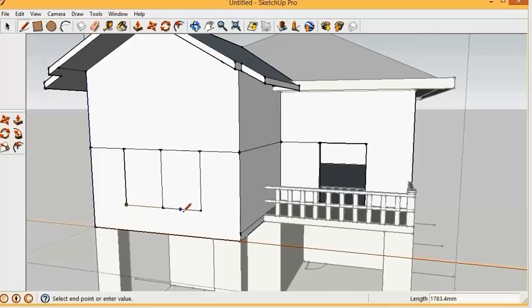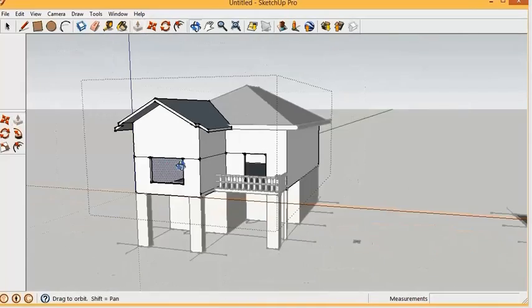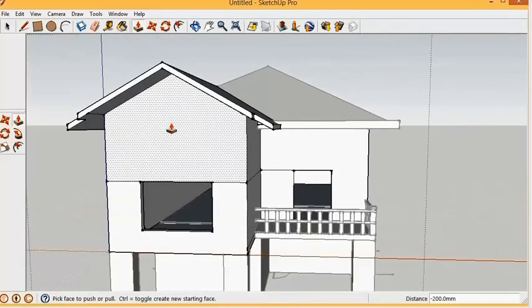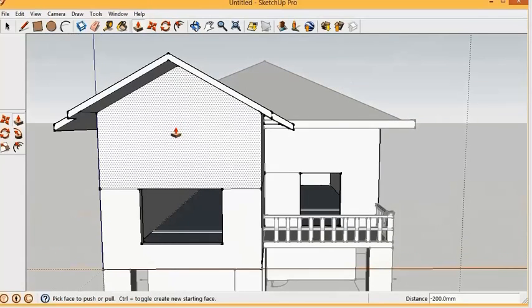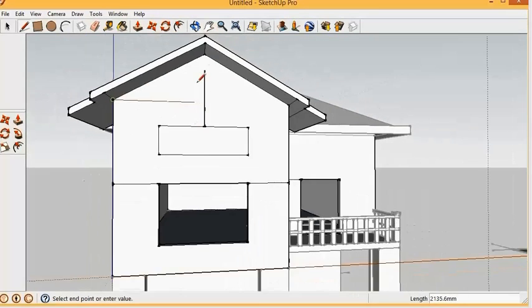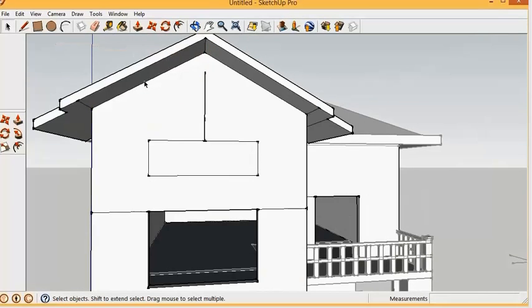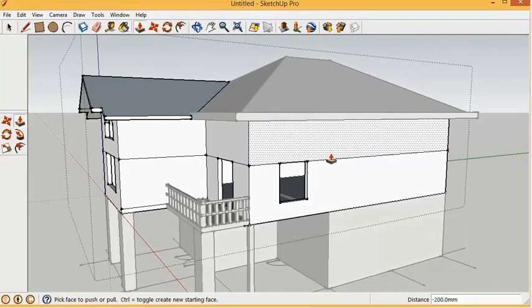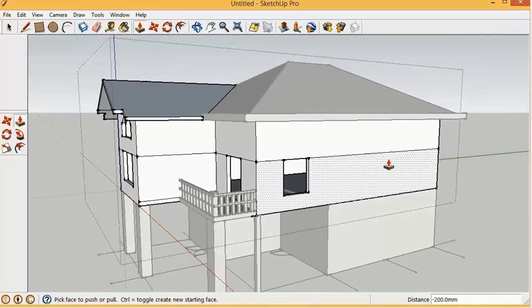Now we can view these more clearly just by going into View, Hidden Geometry. And when we turn this on, it shows dotted lines for what we call softened edges. And it basically allows me to soften these edges. And then I can also smooth the normals between these. So if you can catch this in the light, when we toggle this on and off, notice how it becomes a hidden edge but a flat face, or we can smooth it to make it look even more round. And then the angle between the normals is basically screwed along a path to create complex objects.